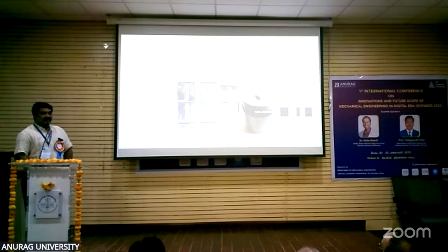Here we are taking some parameters based on speed. We did 9 experiments, and all the welds obtained are of very good quality. The square pin profile has a very good mixing ratio of flow compared to circular pin profiles. That's why this pin is selected for friction stir welding.